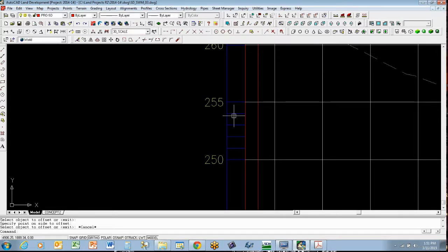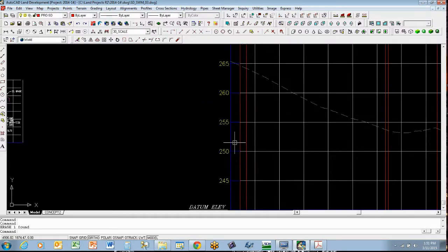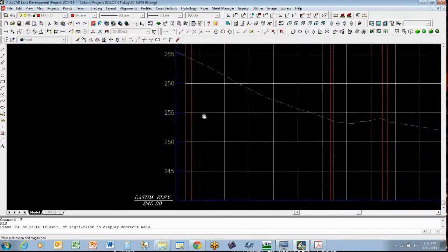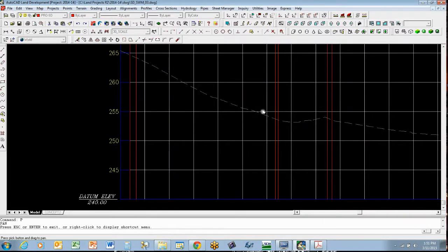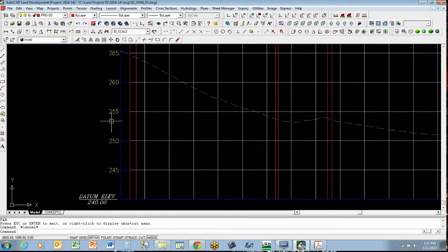So we know now that 6 is the vertical scale unit factor. So all of our computations have to be based upon 6, because now we need to start setting in the inverts of these structures based upon the elevations given to you by the engineer.